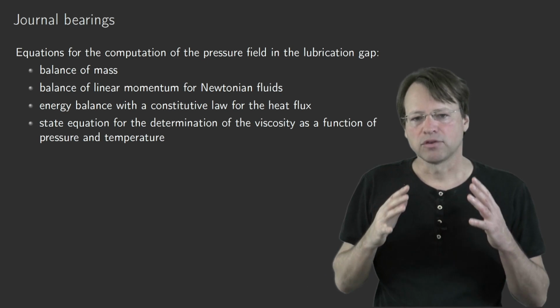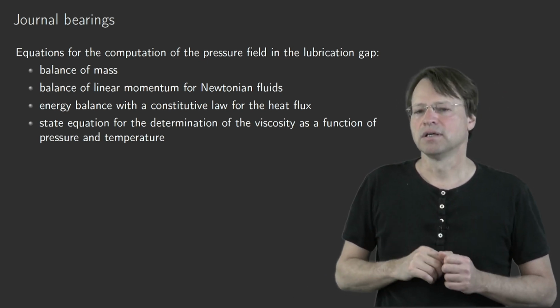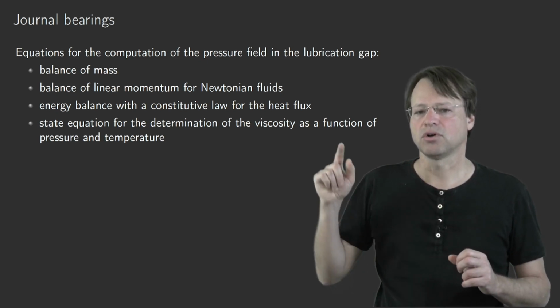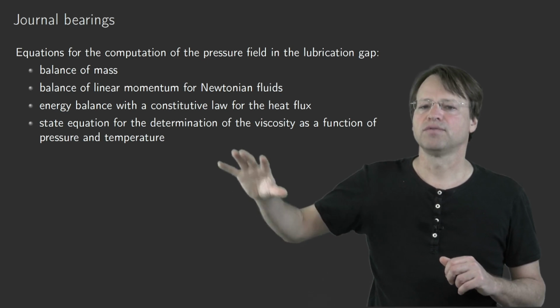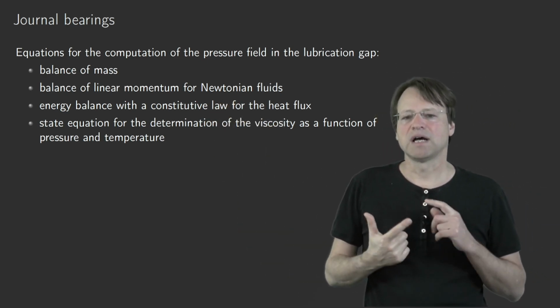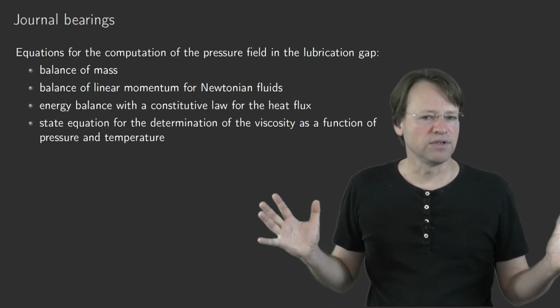And therefore, these two effects will more or less cancel each other, and we do not consider the temperature dependence of the viscosity, and therefore we drop the last two equations. So we are left with the balance of mass and with the balance of linear momentum. That's even difficult enough.